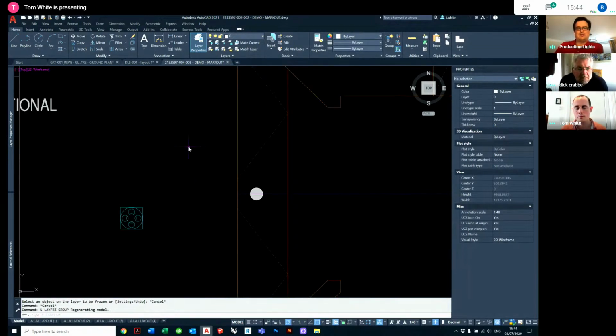I think, Tom, we should just very quickly explain what purge does. It cleans and wipes away from the drawing. It's removing stuff that hasn't been deleted, but the drawing's still holding information within it. It's removing anything that's not used. And Tom's example of layers is a classic one. If you've got a template drawing with a load of template layers, and you have layer purge selected, if you haven't put something on your XREF layer for sound, it will wipe the layer away. So just when you are purging, have some caution, which I think Tom is explaining anyway. Sorry, butted in. No, yeah, absolutely. Of course, I fully agree with you.